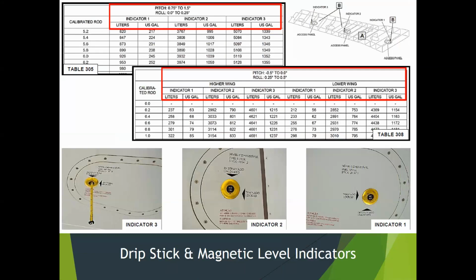This is not the same hydrometer. You have a hydrometer for fuel. It's got a different calibration scale on it than the hydrometer that you used for batteries, but it's the same type of tool. You fill the little vial with fluid. You put the little floaty stick thing in it, and you measure where it floats to tell you what the density of the fuel is. You got the stick with the float on the bottom that moves up, and everyone remembers what it looks like.